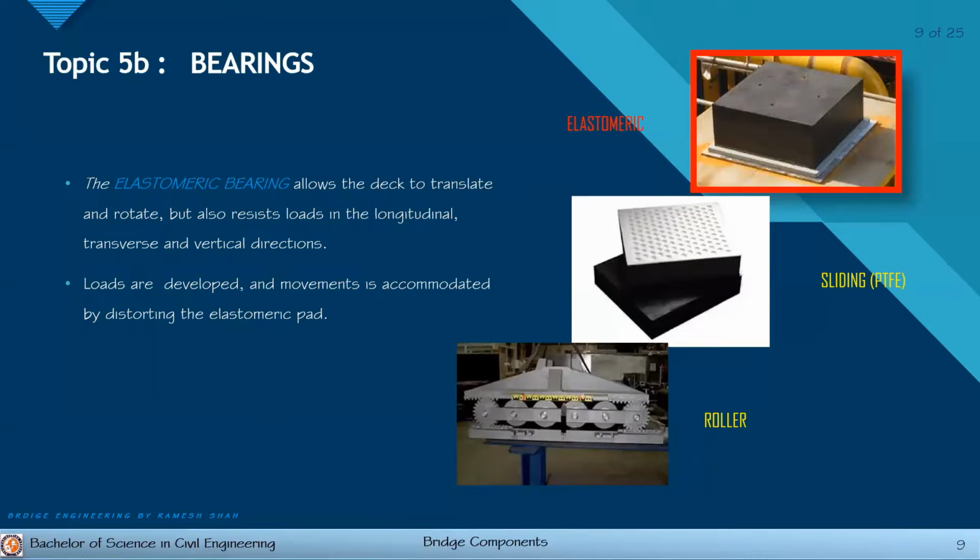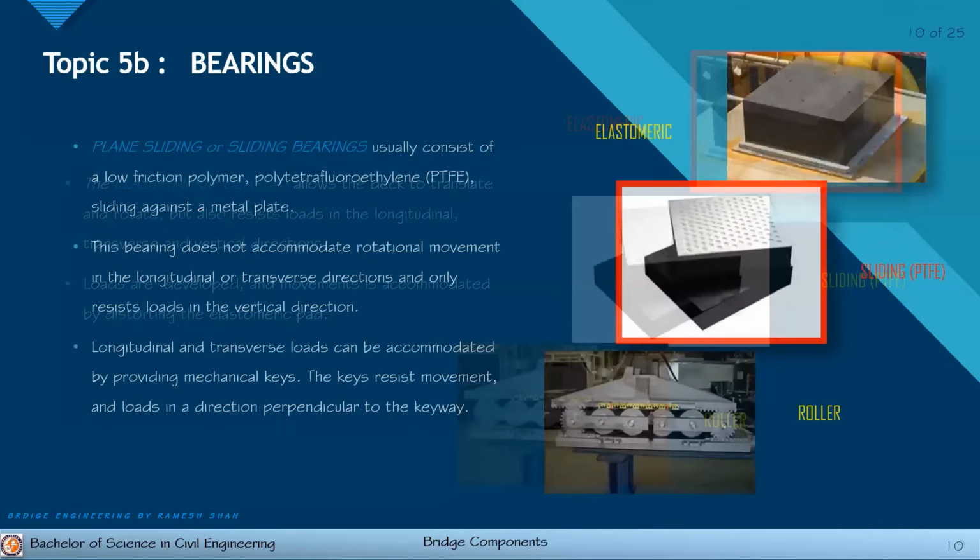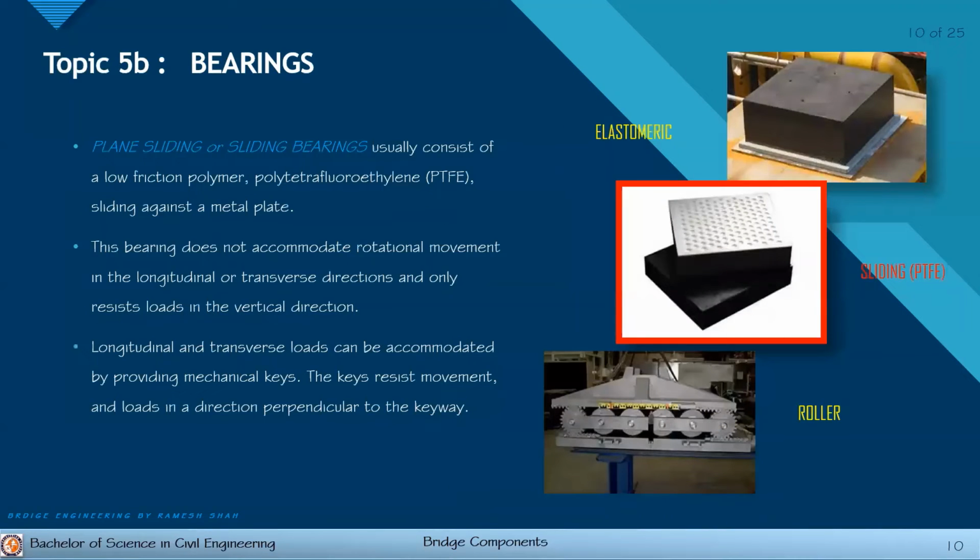For the elastomeric bearing, this one is resisting the loads in the longitudinal and transverse and vertical direction. But however, it allows the deck to translate and rotate. Yan ang purpose niya. So let's proceed with the sliding PTFE.